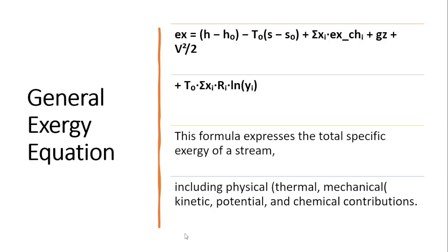About the general exergy equation, you can see the general exergy equation, which is divided into several terms. I should emphasize that subscript zero means the dead state, because in calculating the exergy we must have one criterion, and in this case the criterion is the dead state.